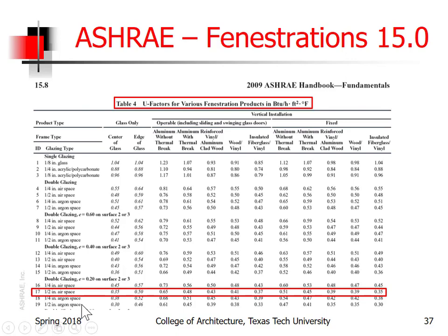Argon is a gas that they put inside double pane windows. It's an inert gas, so it doesn't transfer energy as easily, so it's a better insulator. And you'll see in many cases this will be a more effective U factor, a lower U factor than just air itself, dry air.